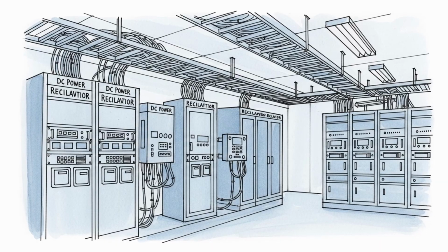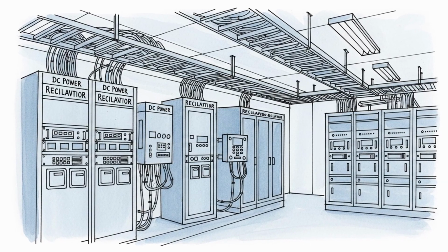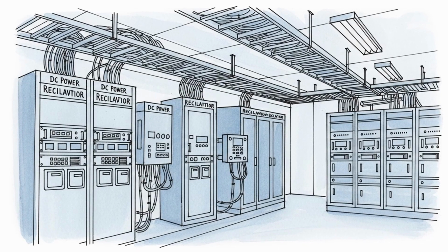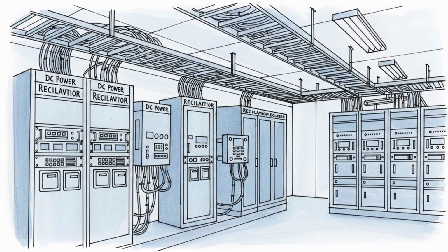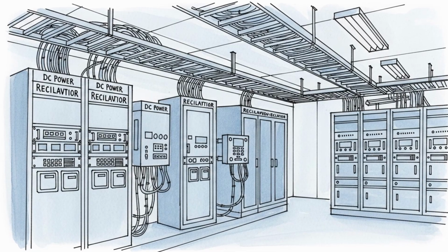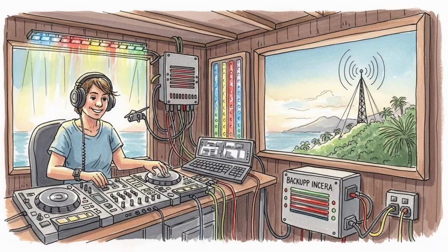Ground dB by dt peaks. Induced electric fields rise. Long conductors see quasi-direct currents. Transformers enter partial saturation. Harmonics increase. Protective devices reach limits. If reactive reserves are low, voltage support is lost.